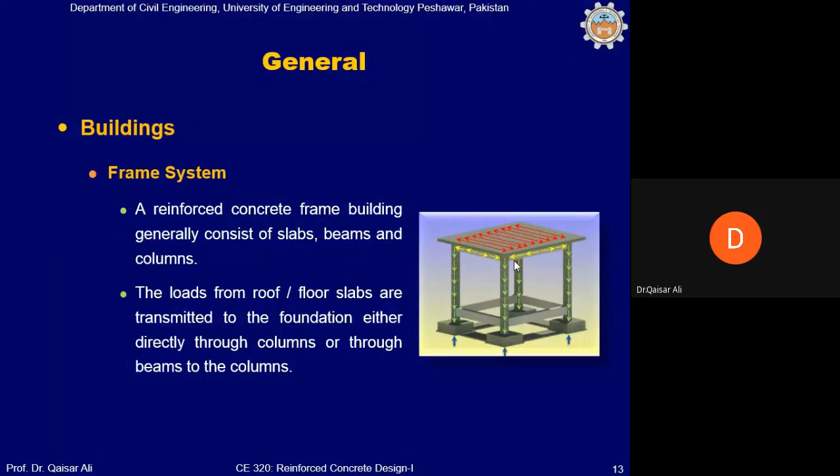Okay, so the foundation, particularly in this case as shown in this slide, is an isolated footing, and the foundation will be bent at the edges, and the bending moment will be such that tensile stress will be produced in the lower part of the foundation pad, and compression stress will be produced in the upper part of the pad. And it is possible to design structures without beams, where the slab will be directly resting on columns. It is possible.